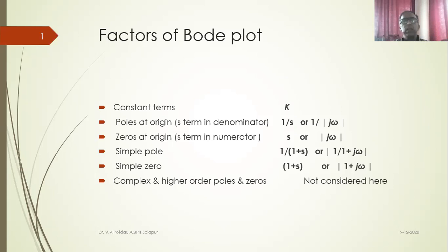If you cross the limiting value of K, the steady state gain value, beyond this value the system will tend to become unstable. So this is the benefit of all these frequency response plots and pole zero plots. We can get to know about the system performance characteristics and we can improve upon the system behavior.